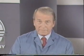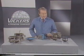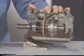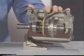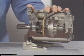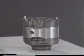With pressure plate loading being a function of system pressure, it's only necessary to tighten the cover bolts to their specified torque. But don't forget the little spring and O-ring seals. Now we come to the other type of vane pump, the intravane series. This one is a truly high-performance unit with deliveries up to 109 GPM and pressure to 2,500 psi, 3,000 psi in smaller units. It is a cartridge-type pump where the ring, rotor, and vanes are contained between a pressure and wear plate, held together by two small screws.